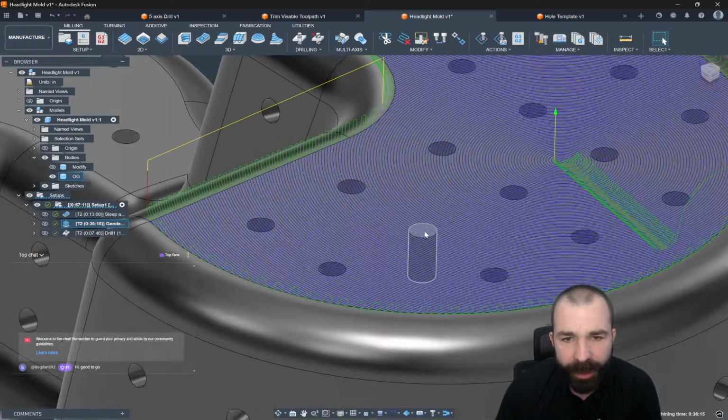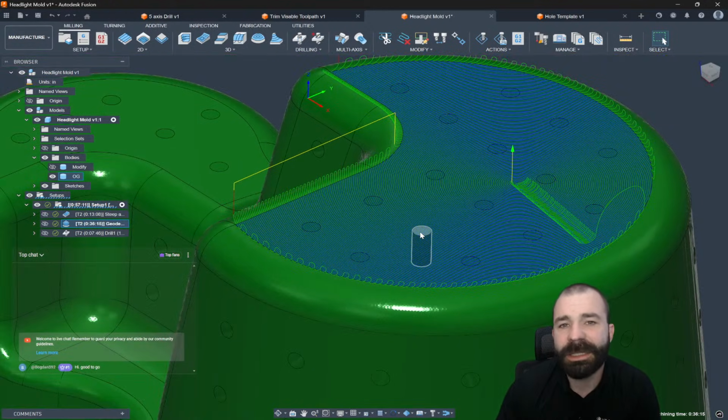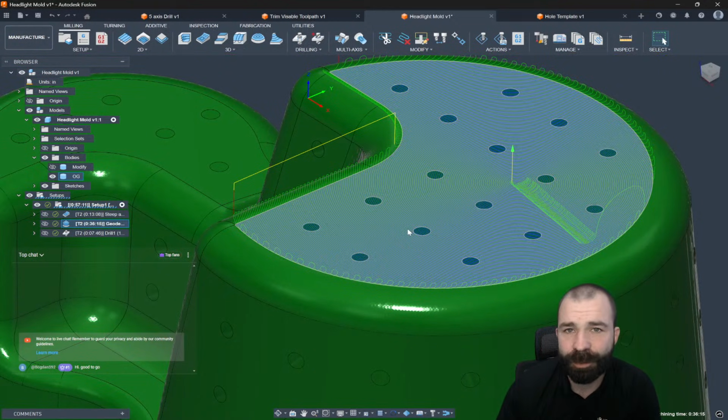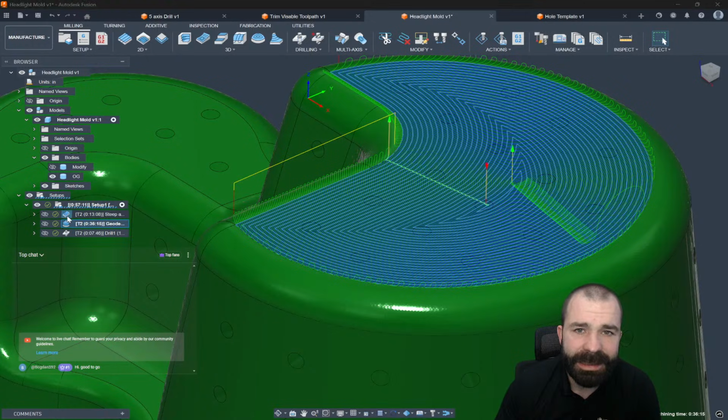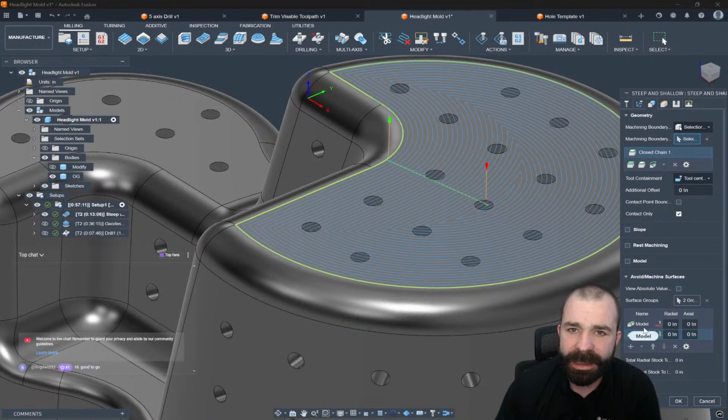Now we're going right over top of our holes. Again, if your toolpath is driven by surfaces, you're going to notice that I have that ability to just check that box where I define my surfaces versus utilizing my avoid touch machining settings. Now that does lead me into pointing out here is there is now the ability to take your groups and quickly create a selection set.